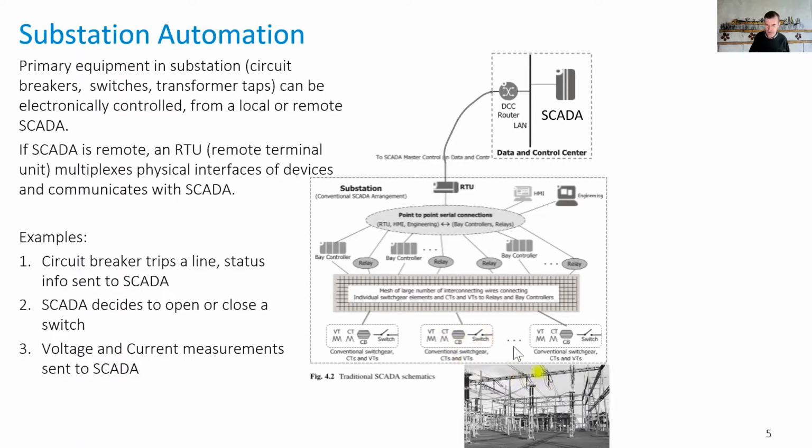The switches are used for reconnecting the grid when there is, for example, an outage somewhere, or a big change in the power flows that requires you to change the connection of the grid. The circuit breakers are the safety mechanisms used to open a line when there is a condition, for example, congestion or a fault somewhere on the line.